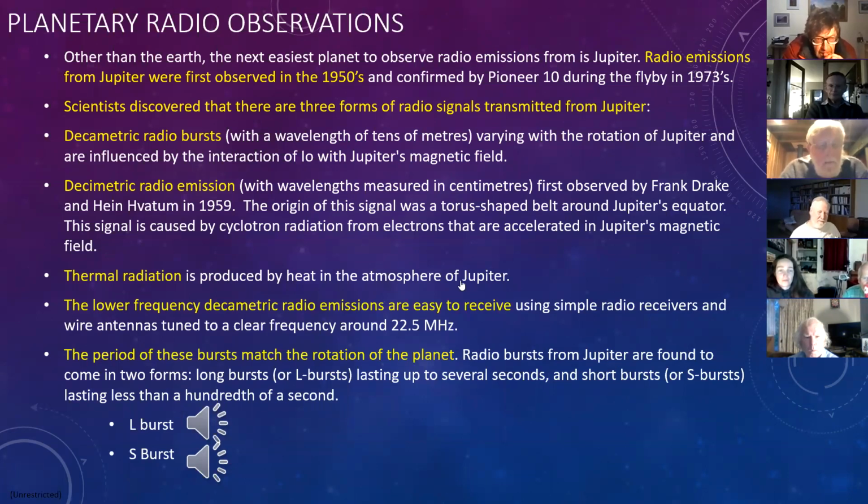Okay. Terry says, what antenna lengths for those VLF receivers? I think 8 to 10 feet, actually, Terry. They're not huge, and they're designed for short antennas for schools. Obviously, not everybody can put up hundreds of meters of wire, because the wavelength at say 50 kilohertz is many thousands of meters, which not everybody can run wire out for.